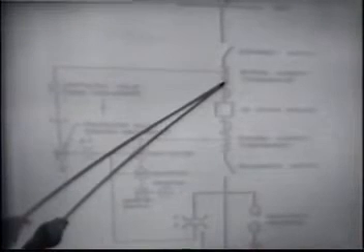The magnitude of the normal current rating flowing through the breaker, 600 amps is a typical value. 1200 amperes is another standard oil circuit breaker rating.